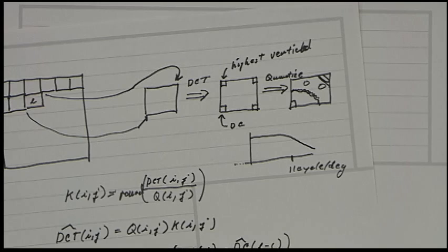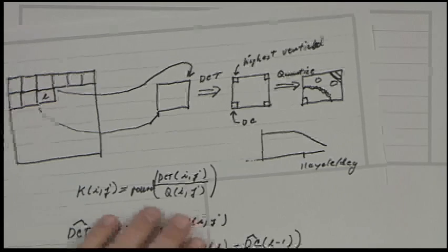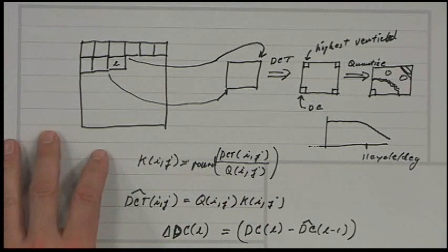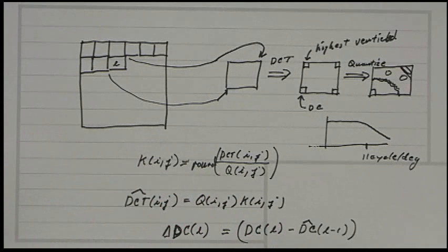Yeah? Why don't we just filter these high frequencies with a smoothing filter and then pass them through the DCT? Well, because then you'll lose high-frequency image detail. If you knew that there were no high frequencies, you would just subsample the signal at a lower frequency and throw a lot of pixels away, right?